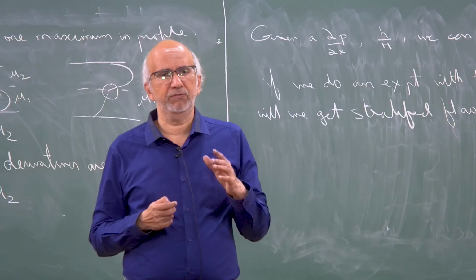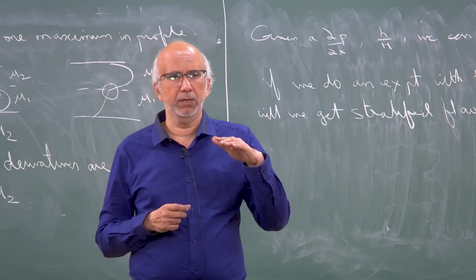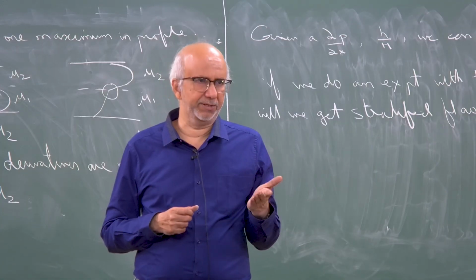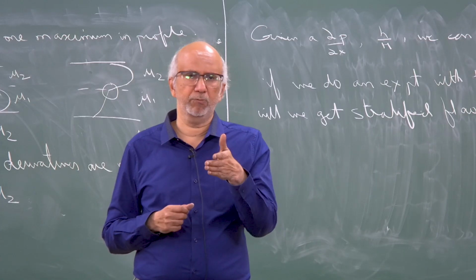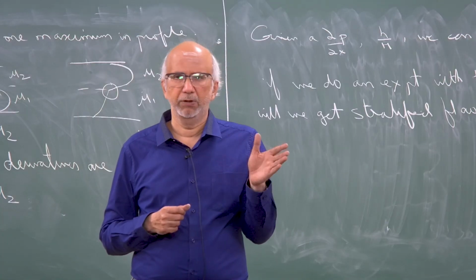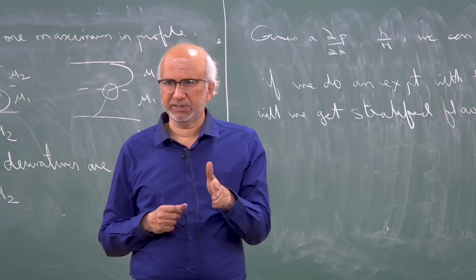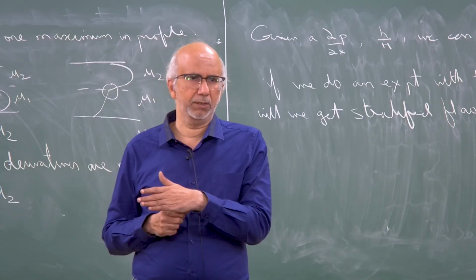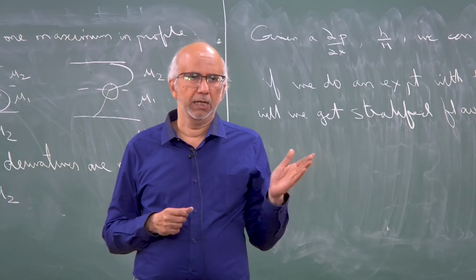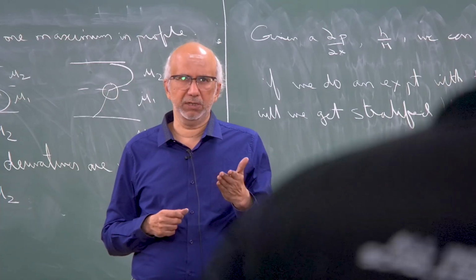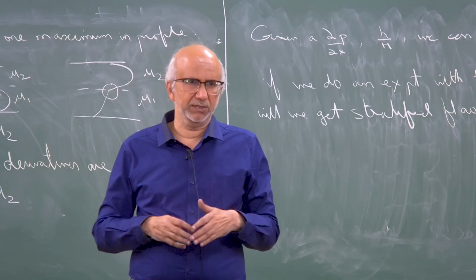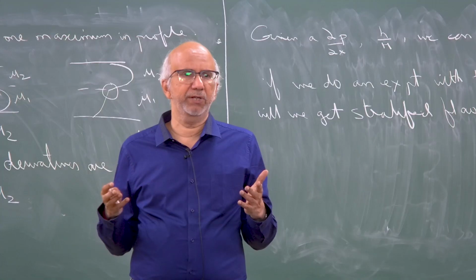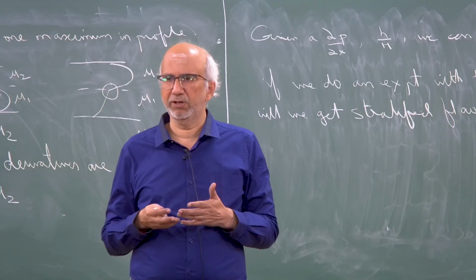If the disturbance keeps growing, then you have an unstable state. This is exactly like what you do in process control. You give a small disturbance at a steady state, and if the disturbance grows, you have instability. Same thing here. If you give a small disturbance to the stratified flow, maybe the disturbance at this interface will grow, and you may have instability. So, you won't be able to see stratified flow.